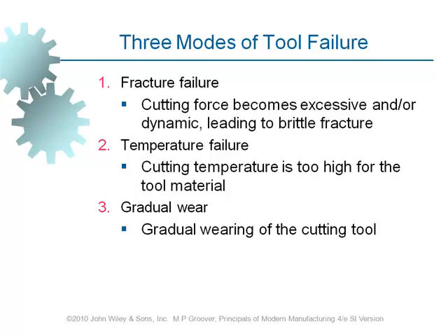None of those are desirable, right? Because we want to have a cutting tool which works and lasts forever. However, unfortunately, we don't have that technology at this time at least. So we've got to choose one. And if this is the case, what Brock said makes sense. Meaning that we are after gradual failure if the cutting tool has to fail, which is the case.